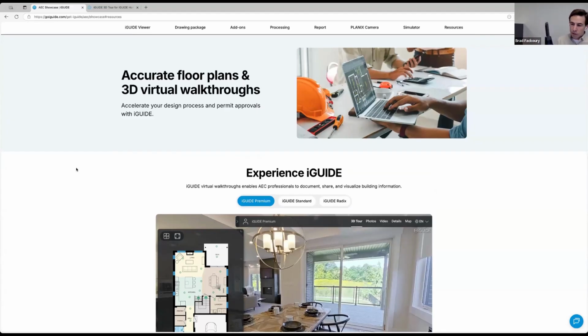So I've got the R1 here in front of me as well. Again, just a general high level recap. Of course, the R1 offers the 360 visuals with the time of flight LiDAR, which gives us the accurate floor plans and the 3D virtual tour. When we get into advanced deliverables, we use that LiDAR to capture a lot of them. And again, it's 2D planar LiDAR. But as many of you know, if you rotate the R1 on its side, you're now capturing vertical data, building sections or vertical profiles. And that data is super valuable when we're creating exterior elevations, if we're going for really accurate RCP plans, or of course the 3D model where we need that data to build it out accurately for you.